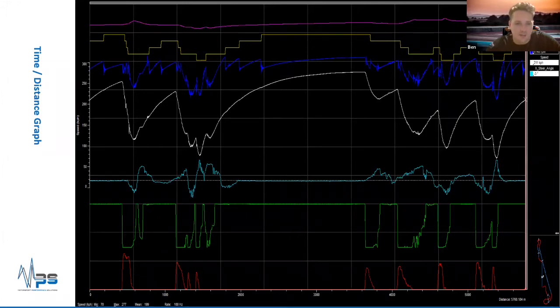So yeah, I would recommend tiling your data, and I'd also recommend coming up with your own limits for how you display the data rather than letting the software auto scale. How you come up with those limits is to do as the automatic software would: open up your whole data file, go through it and work out what you expect your maximum value and minimum value to be, and choose an appropriate value based on that.